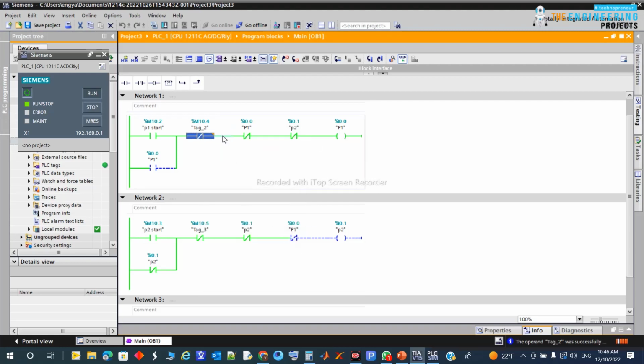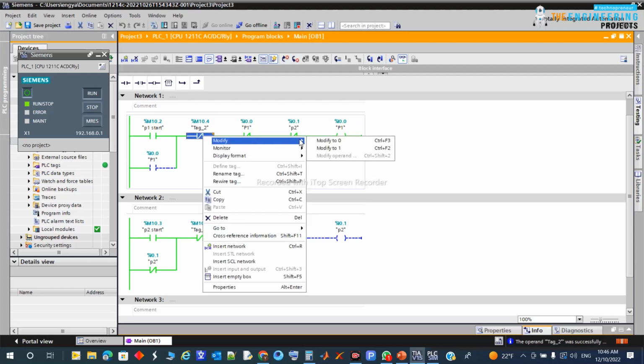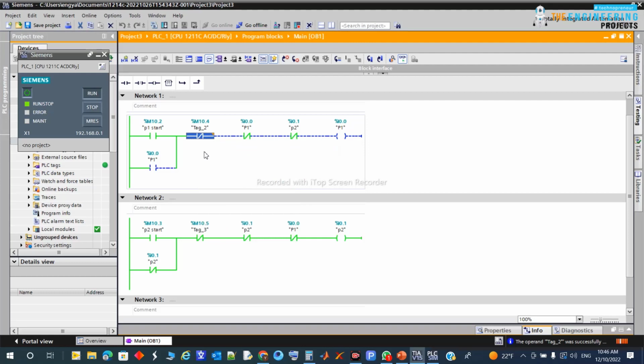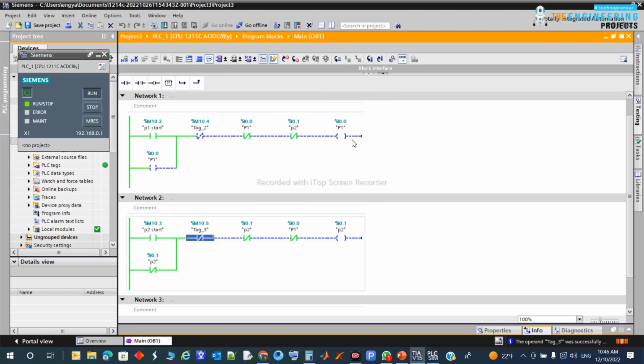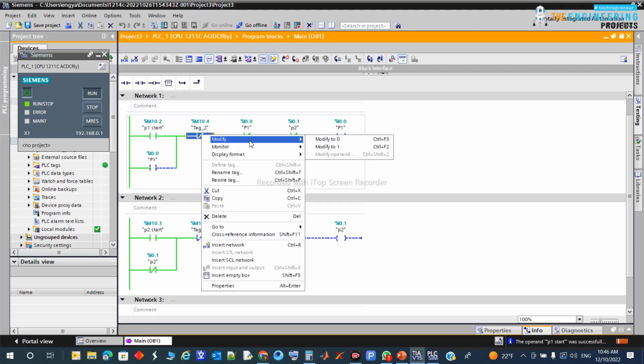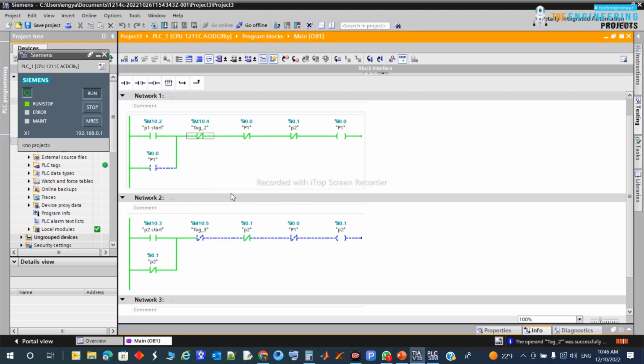Once I stop this one, what happened is, I just stopped this pump, and the other pump is running. Same thing here, if I stop this pump, I need to restart this one again. So I started this one, and for now I force it to true, so I need to force it to end. As you can see here, it is very clear, the interlock here prevents the two pumps from working together.